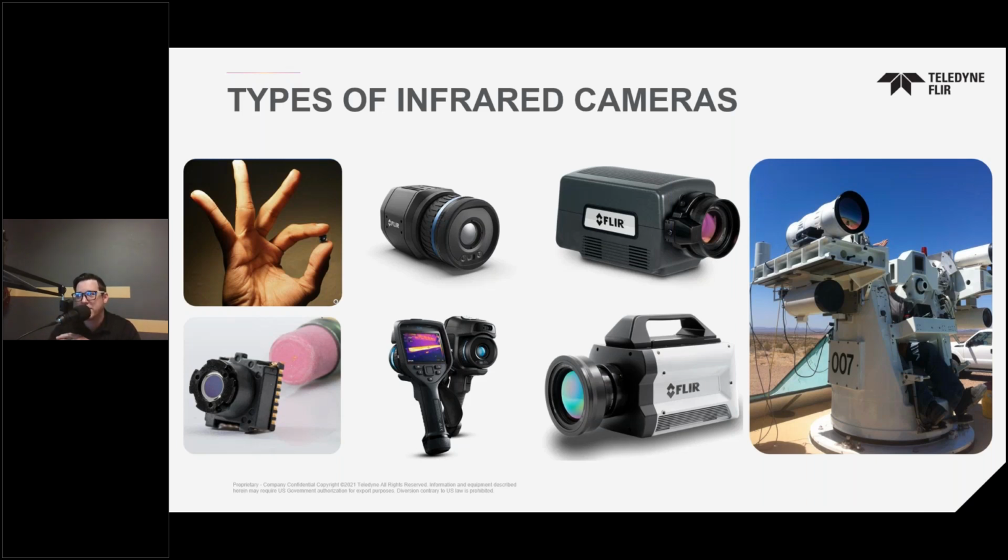On the right-hand side of the chart are examples of cryo-cooled cameras, also called photon counters or quantum detectors. These systems are much higher performance and are typically the models of choice for engineers and scientists due to their capability, their flexibility, and access to the raw data. Whereas the bolometer-based cameras on the left are only sensitive in the long wave bands, the cryo-cooled detector types actually have materials that can cover midwave and long wave, sometimes both, depending on the focal plane array material used.